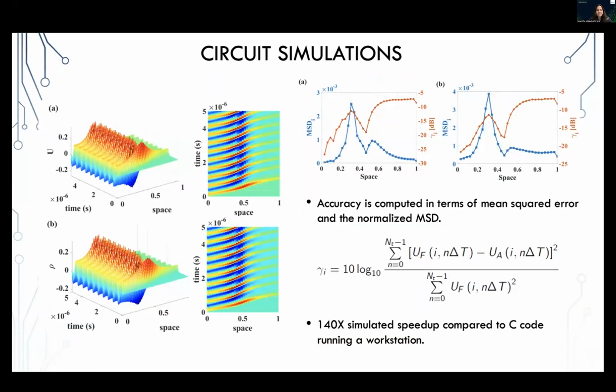Once you have a circuit and the layout done in software, this layout was done using Cadence Virtuoso software. You can also perform circuit simulations and see whether we get the required outputs. These are some simulation results from the circuits for the two variables we were computing, velocity and density, and also from measurements of the chip, we can obtain this kind of results. I will not explain what it is. I just wanted to show you that we can fabricate a chip, mount it on a printed circuit board and perform testing. That is also similar to an embedded system.